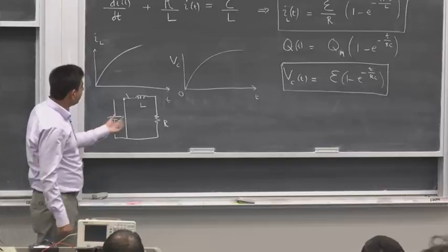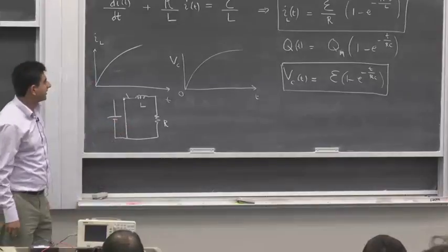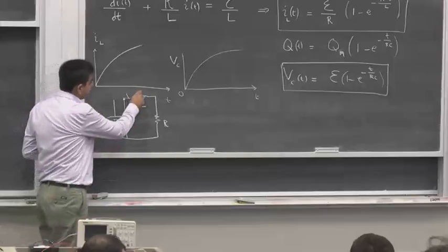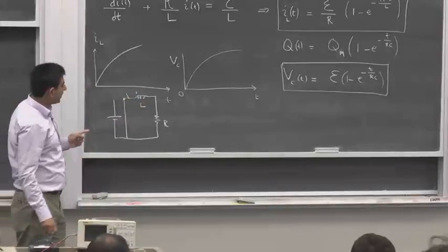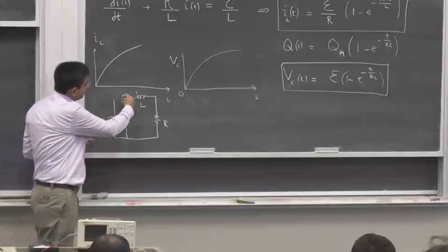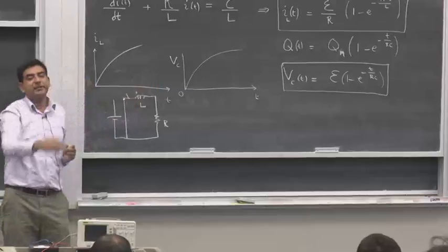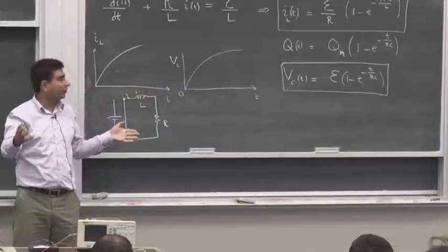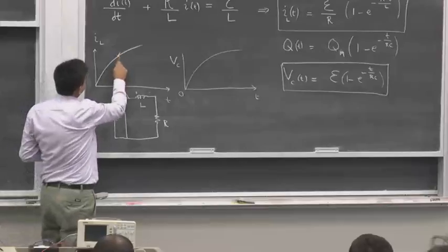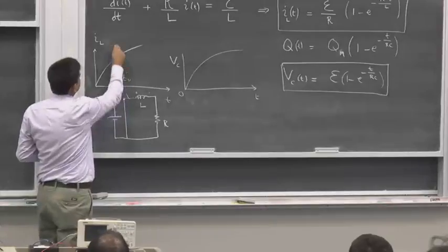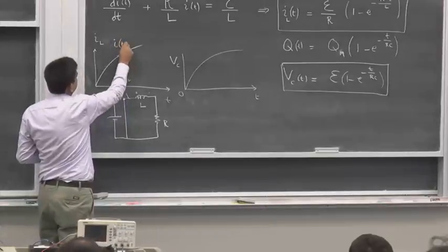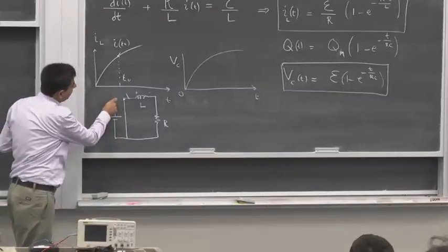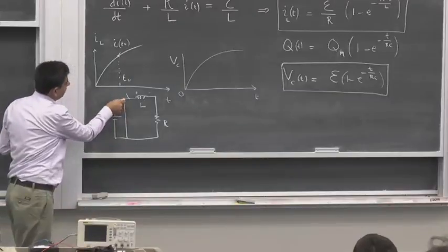So what we have here is a voltage across the inductor. That voltage across this inductor is acting like a source. Now what's going to happen is that if this switch opens up rapidly, there's some current flowing through this circuit. Okay, so we intercept this circuit somewhere at time t naught. There is some current flowing through the circuit, I at time t naught. Then what we would like to do, so there was current flowing here, to open a switch here.